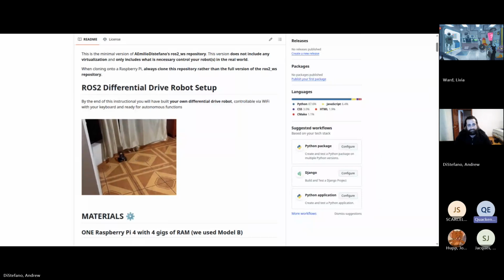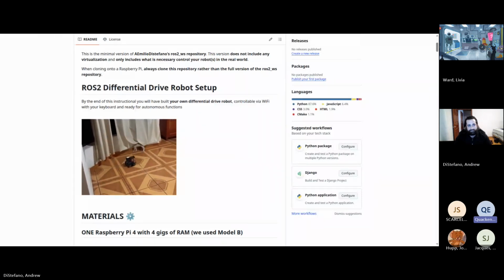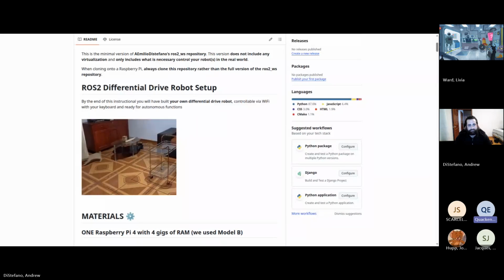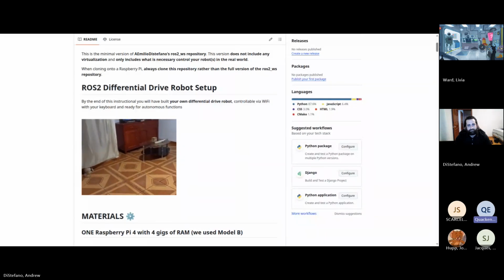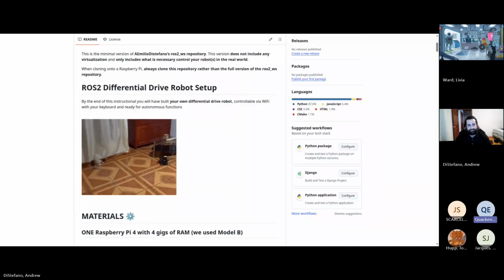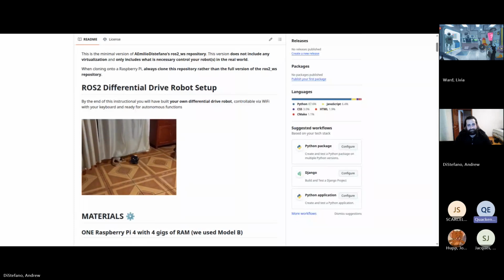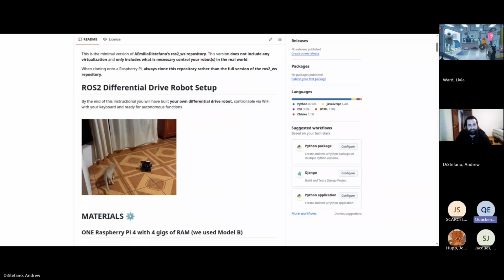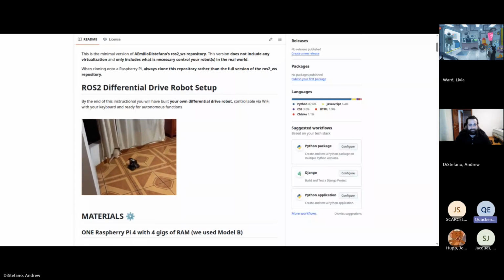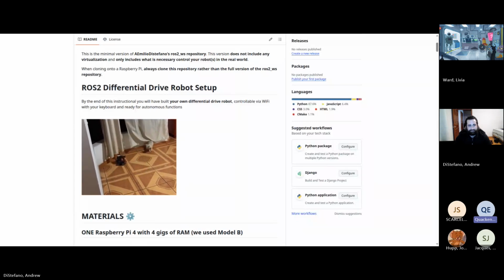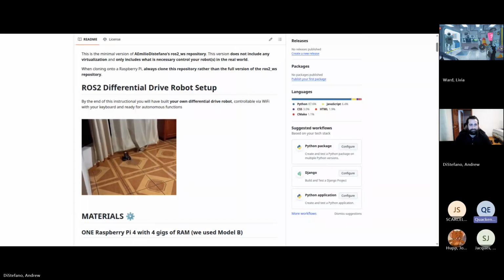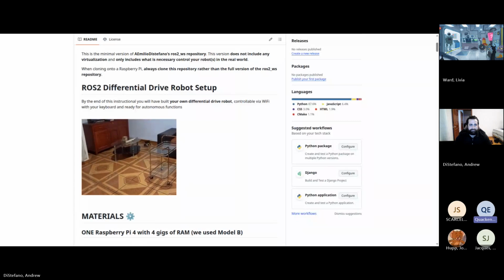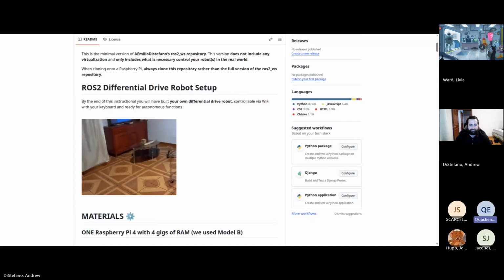Well, there's actually a Chinese specification that works at 433, but usually for the EU it's 868 megahertz, and for the US it's 915 to 928 megahertz. So it's considered sub-gigahertz, so you get wider coverage. As you get up into microwave frequencies at gigahertz and above, like Wi-Fi and Zigbee at 2.4 gigahertz, the signal gets attenuated more in the atmosphere. So being sub-gigahertz is ideal for longer range.